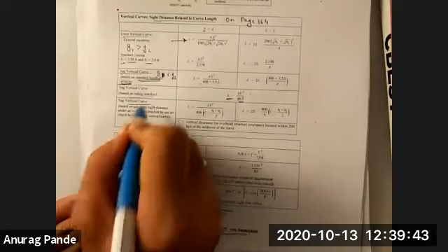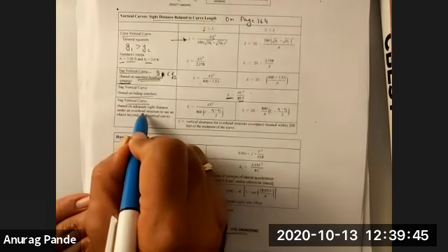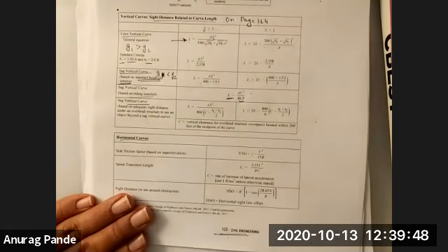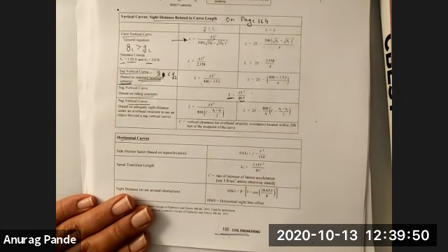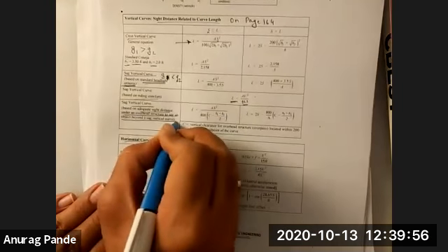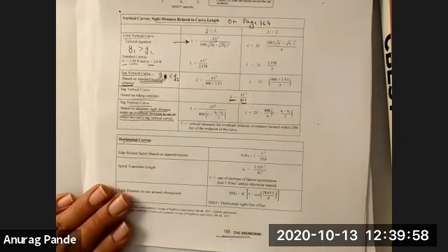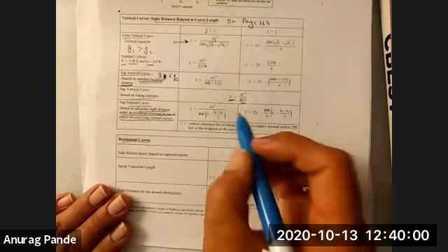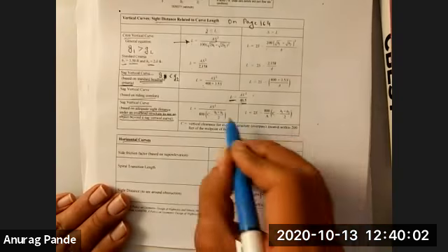And then the sag vertical curve L value is also provided if there is an overhead structure that might potentially cause problems. Based on adequate sight distance under an overhead structure to see the object beyond the sag vertical curve, if an overhead structure might be a problem, then this is the formula there.